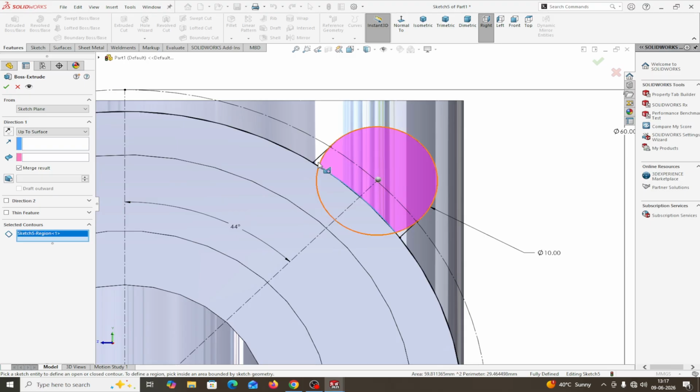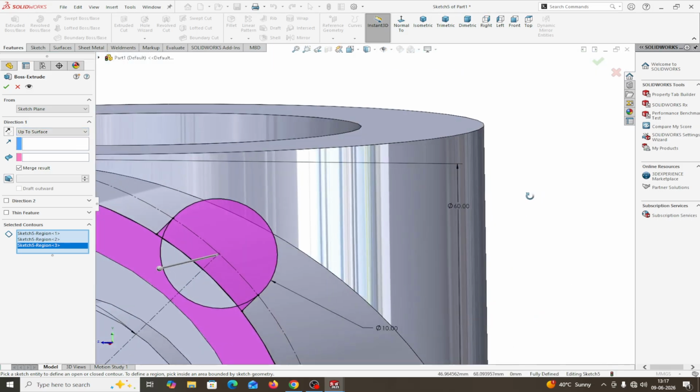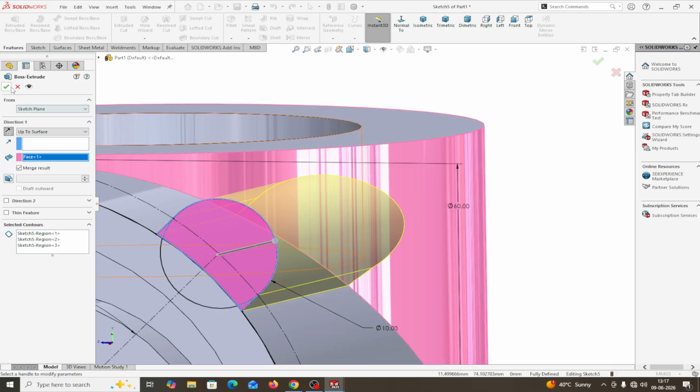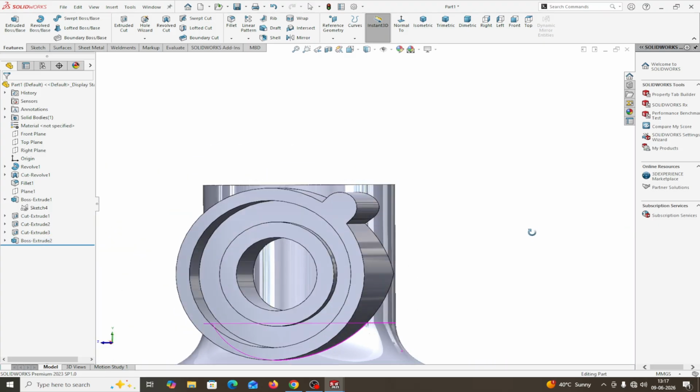This slides, zoom it. This one and slightly zoom it. Either you can trim, otherwise I have to extrude this portion. You please note carefully. But where? Up to surface. Which surface? But direction is coming towards my side, reverse the direction. Up to surface, which surface? This surface. This. Now I have made this one. Now I will make the threaded hole of M5.